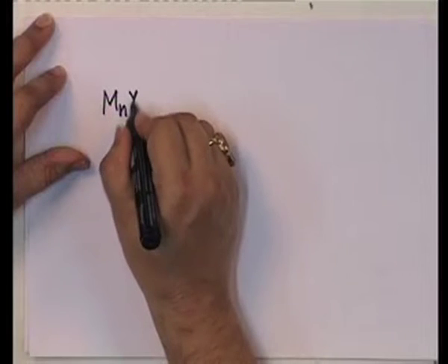Now, let us look at the damped problem. And today, I shall only introduce you to the concept of the damping. And remember, I talked about proportional damping. Well, we will see. If you look at this, by using mode superposition, we are getting the equation which looks like Mn yn double dot plus omega n squared Mn yn is equal to Pn. This is a single degree of freedom. It is an undamped single degree of freedom. So, now if I want to include damping at the single degree of freedom level, how should it look? It should look like this.